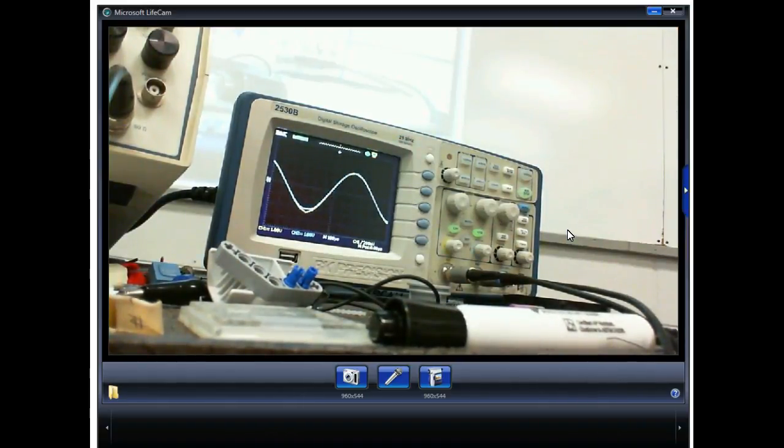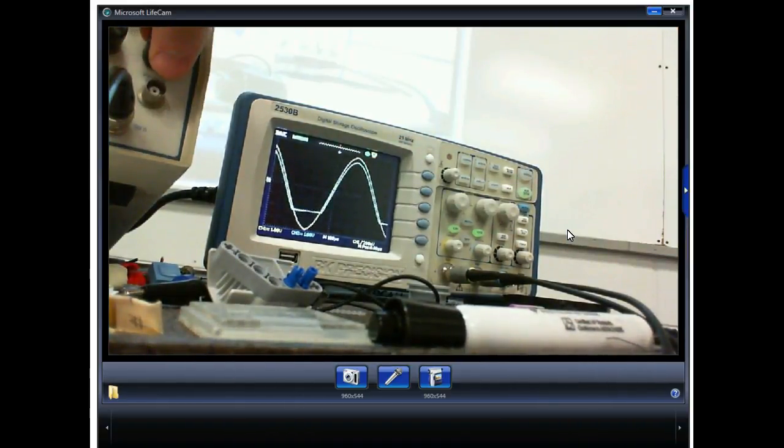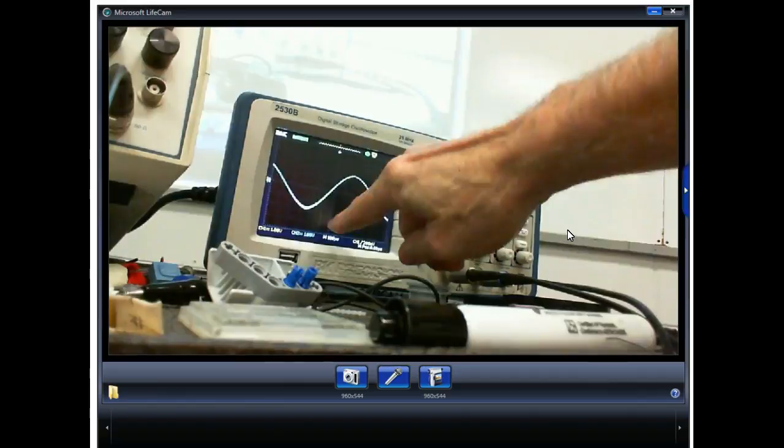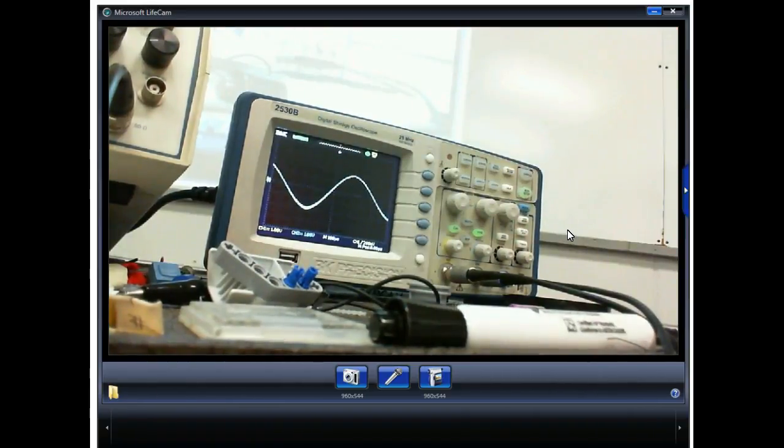I don't have a problem in it right now, but you can see we're actually putting too much in the amplifier than it can handle. So what I'm doing is raising the input right before it starts saturating down here. And then when I open up R2, the output don't change at all. So I'm going to have to think about that. That's not what I expected.